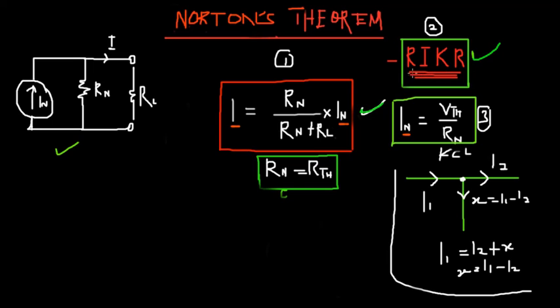R is what you remove, I is insert, K is what you do using Kirchhoff's, and R is finding either the Thevenin or Norton's resistor. And then we implement our Ohm's law. But this is a technique I usually use in solving Norton's theorem. That makes the work a bit easier and straightforward, so we implement Thevenin in solving Norton's question. Now let's dive right into this video.